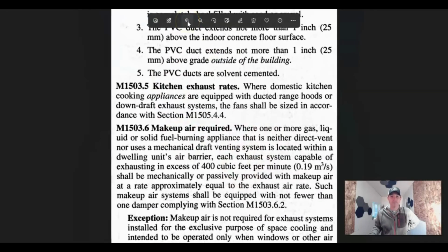Let's talk about makeup air. You should not, in most instances, especially on just residential houses, run into a situation where you need makeup air. I mean, you have to have a pretty big hood fan, which in some really nice houses with really big hood fans, I could see that happening. But for most do-it-yourselfers, you're putting in a micro hood, maybe a decorative hood that just kind of sits over the top of your range. It's not going to be over 400 CFM. But if it was, you'd be required to provide makeup air.